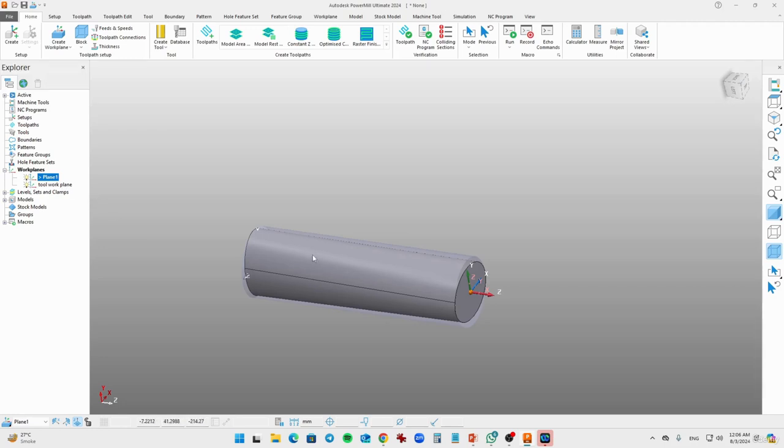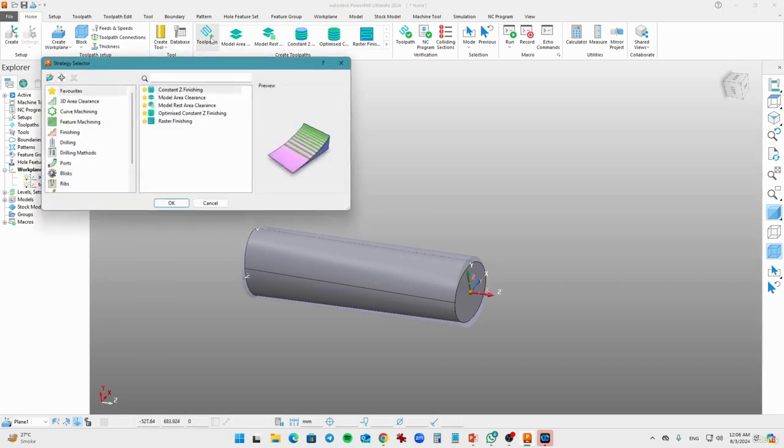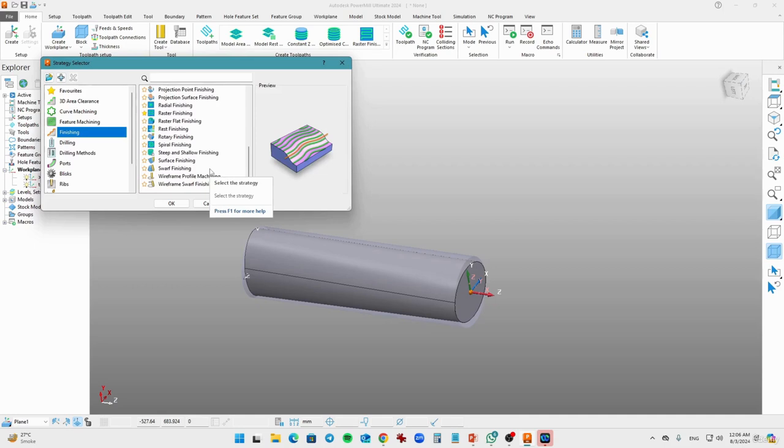Right now the work plane which is active is the active work plane for the block. So now just go to the toolpaths and create the toolpath. You will find the rotary tool axis toolpath in the finishing strategies, and in the finishing strategies you will find the rotary finishing toolpath. As you see, it's a bottle-like shape, and it just gives you an example of how it actually looks. Our model is also related to that, and it will work fine.